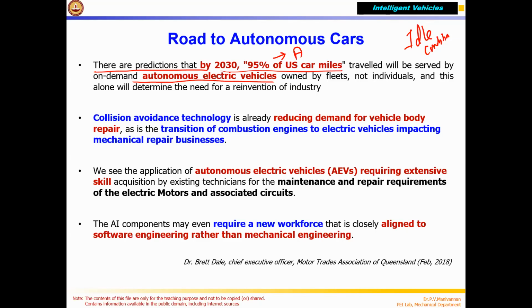So you are ready. Even in cruising condition, which emissions will reduce? Emissions like CO, carbon monoxide, and HC, hydrocarbons. These two will considerably reduce, 40 times. I'm not talking about percentage, 40 times. In idle condition, the CO and HC emission is 40 times more compared to cruising condition.